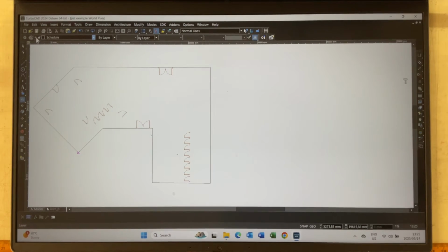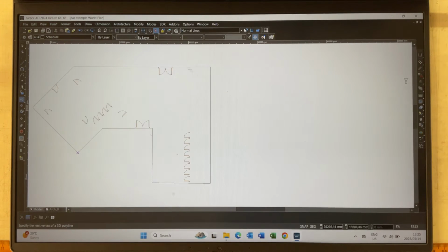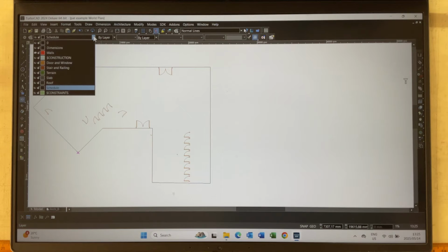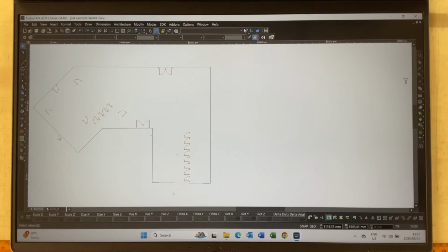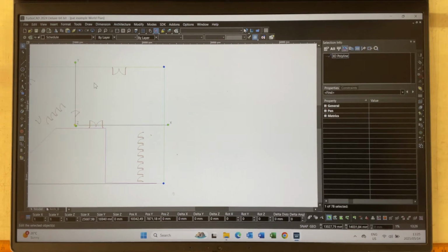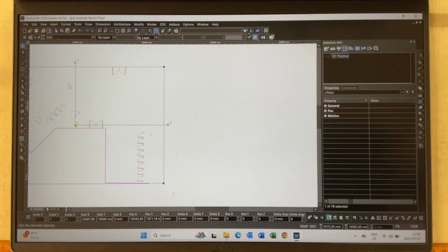Right, so what I'm going to do now is come in over here and you'll see that they actually have a thing called slab over here. So when I'm going to draw this next thing, I'm going to ask it to draw this thing as a slab. All right, so I'm going to select first of all that arrow, click on it, and I'm going to change that so that it is going to be a slab. Right, okay, that polyline is now a slab.